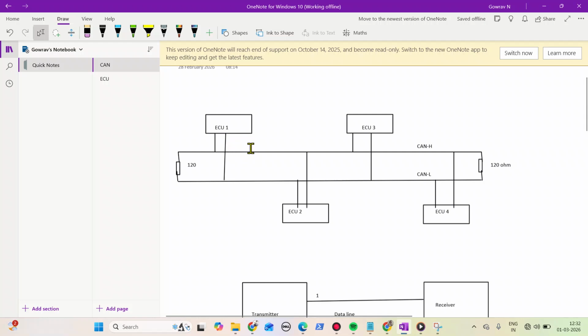Okay, so it reached till here. In the next time, this ECU is transmitting again some 2.5 volts only. Now this 2.5 volts is traveling here, and the first 2.5 volts has reached here, and it will be reflected back and come in the backward direction. The second transmitted 2.5 volts will come here, and they will intersect or collide or something like that.